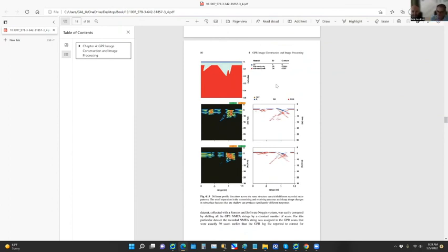Going in two different directions on a site, or even on a structure, you'll get two different profiles. They're not symmetric, and that has to do with the fact that you have a transmitter and a receiver that are separated horizontally. If they were co-located, going in two directions you'd get the exact same profile, but you don't because they're separated. Here's a simulation made off this structure, with the transmitter and the receiver going in two different directions, and you get something that looks a little different.